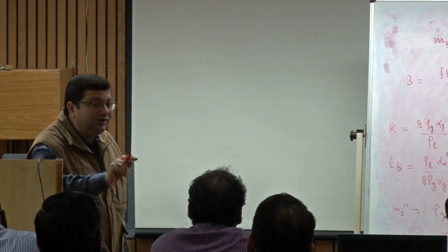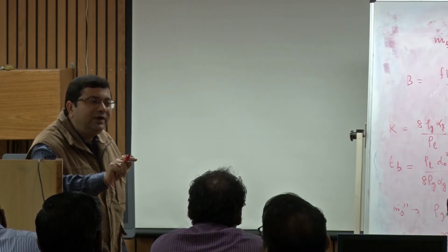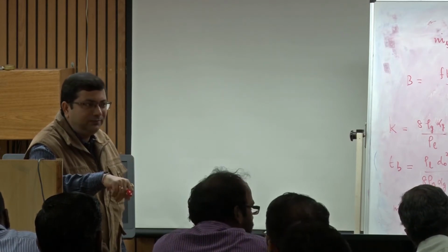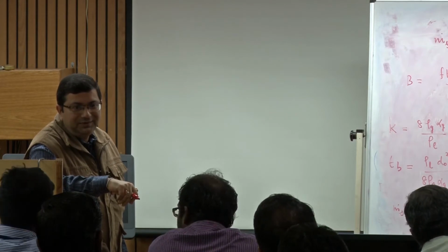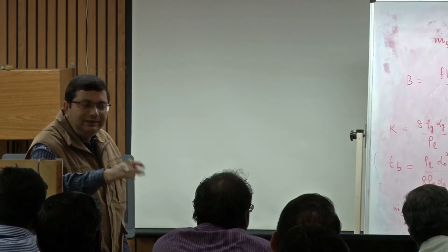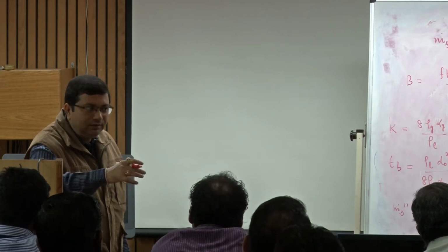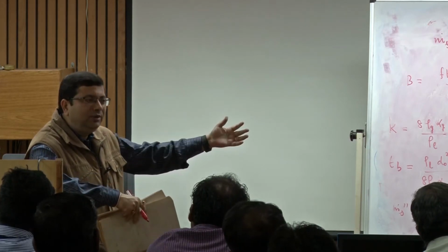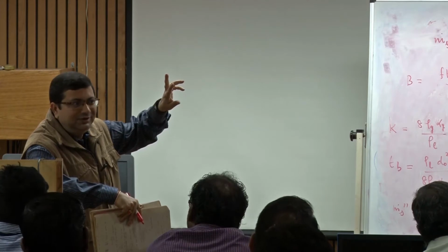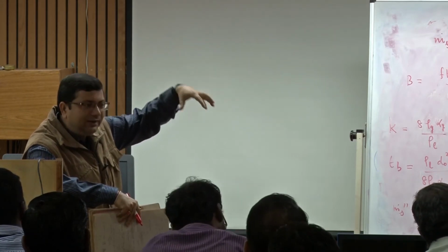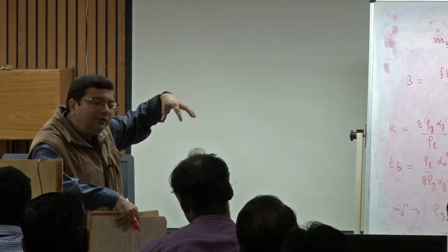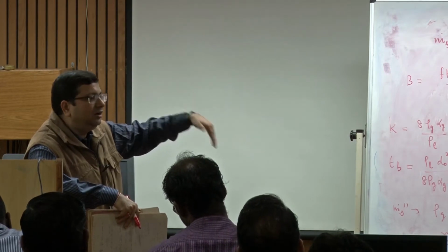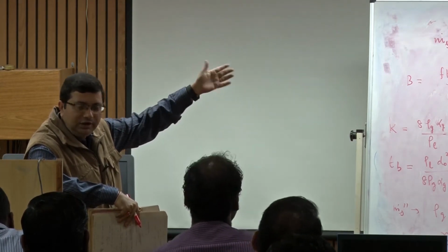This concept will come very soon in automobiles, particularly diesel engines. Diesel has a much lower evaporation rate compared to lighter hydrocarbons like heptane. So, now people are talking about supercritical combustion, supercritical atomization, where a fuel like diesel is mixed with a certain amount of lighter hydrocarbon. Therefore, the overall value of L reduces, and we get better combustion efficiency and lower emissions.